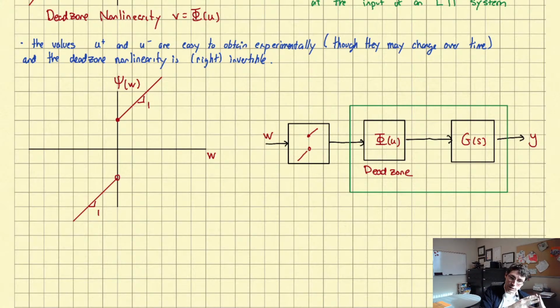The linearization-based approach that we talked about at the start of this chapter relies on approximation, and so the region in which it's going to be effective is smaller in principle. However, because you're using feedback around your linearized model, it tends to be more robust. So you're trading off a little bit of robustness for possibly larger regions where your controller is effective.